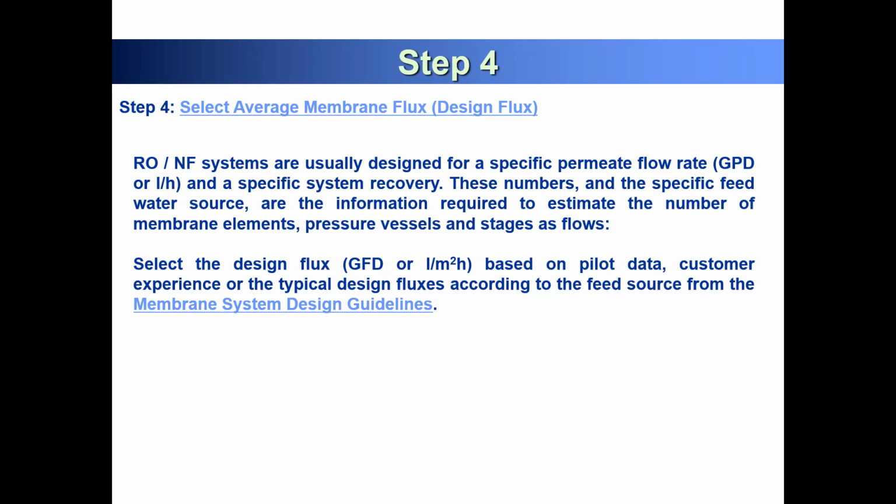Base it on pilot data or customer experience, or the typical design fluxes according to the feed source from the membrane system design guideline. If you click this membrane system design guideline, you can see this type of element has 20 LMH as the best for wastewater reuse. Also for the SWHR membrane module, 40 LMH would be the best to design your average membrane water flux.